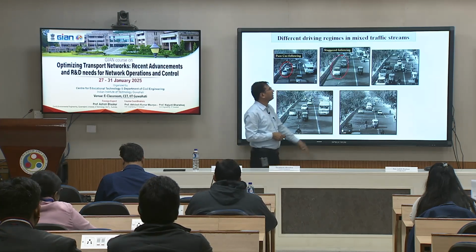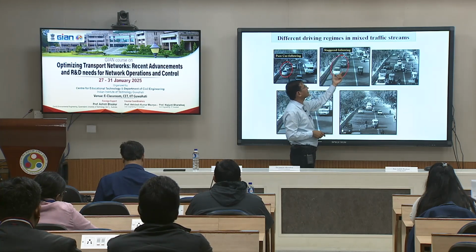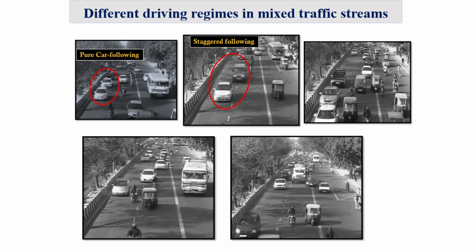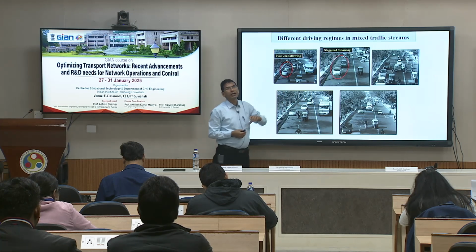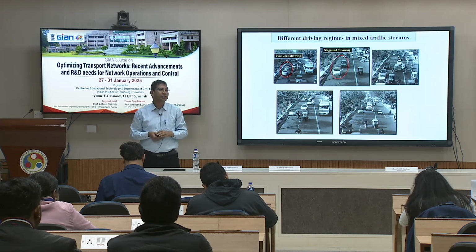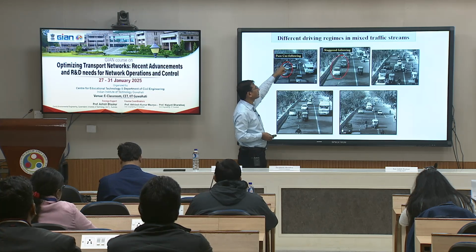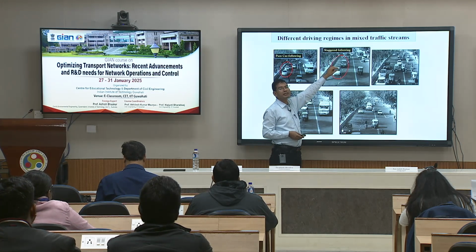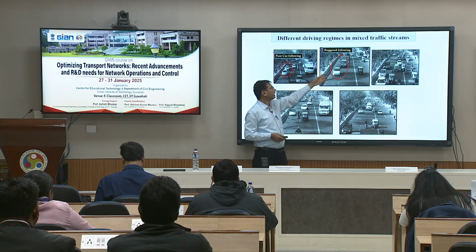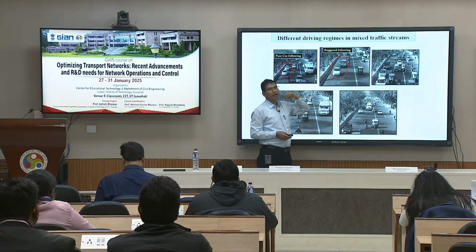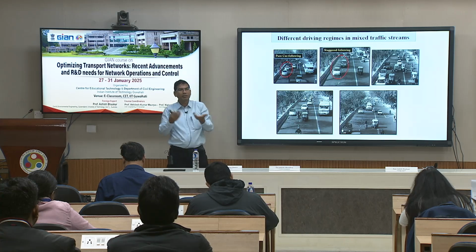But in the Indian context, because we are not following lane discipline, majority of the time you will see that one vehicle is followed by another vehicle, but the following vehicle is not exactly behind, it is slightly shifted laterally. So in this case, traditional car following rules may not be appropriate, because whatever distance headway you maintain here, you may not need that kind of distance headway here. If you collect the data and assume that these two are in car following mode, you will be surprised to know that the time headway might be only 0.2 second.